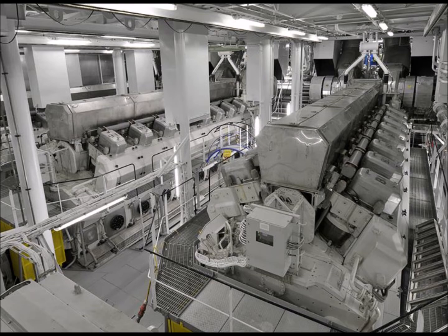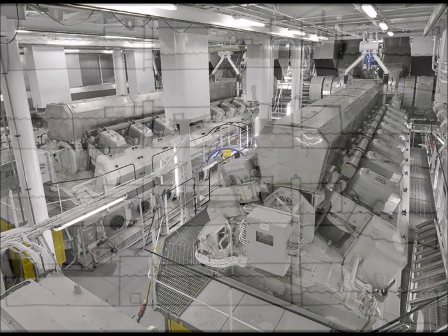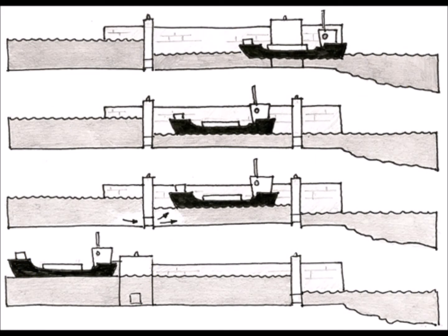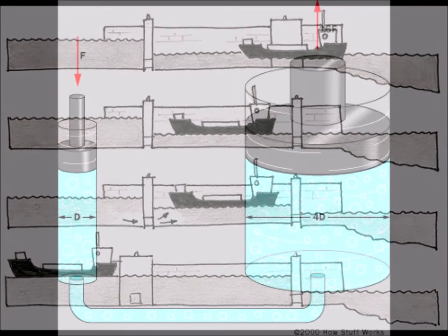One of the things we learned a long time ago was the ability of water pressure to raise and lower things, and a lock is an example of it. There is no pump in a lock. All you have to do is open valves. There's a valve on the low side and on the high side. If the ship in this example is going from low to high, you go in, close the doors, and let the water in from upstream, which on its own will fill the lock up to the level without doing anything else. When the lock is properly filled, you just open the door and the boat sails on.